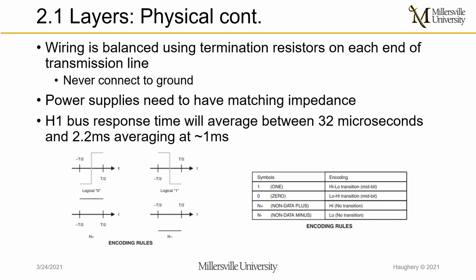Continuing on that, at the end of the transmission wires, termination resistors are used. Also, these wires should never be connected to ground. Power supplies for Fieldbus need to have matching impedance. The H1 bus response time will average between 32 microseconds and 2.2 milliseconds, averaging in at around 1 millisecond.